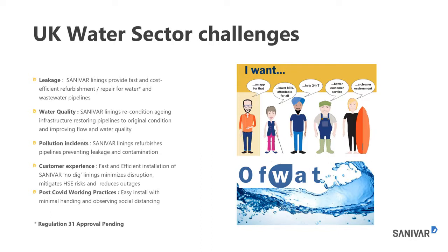This lining technology has a much smaller carbon footprint in terms of excavation and general operations, and it reduces customer outage because of the time it takes to install and refurbish a pipeline using these methods. And topical, as we move into the post-COVID world, the liners are very COVID friendly, for want of a better word, in the fact that they are not labour intensive. They're easy to install with minimal handling and observing social distancing.